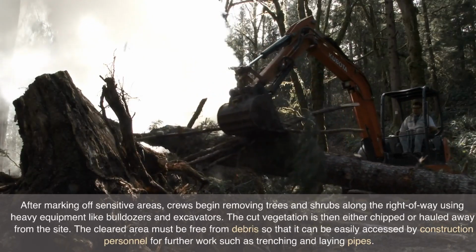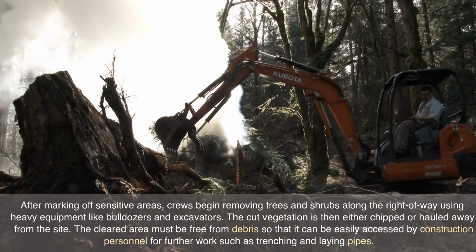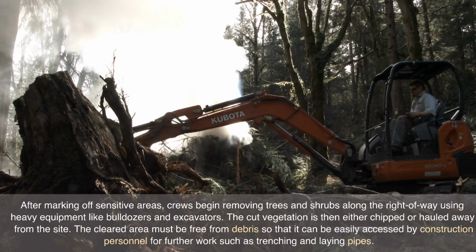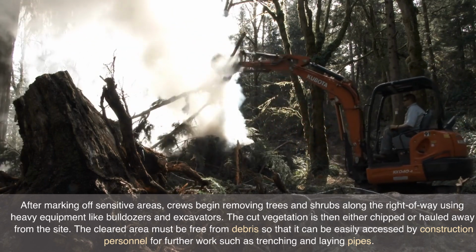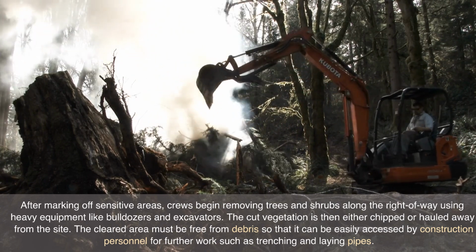After marking off sensitive areas, crews begin removing trees and shrubs along the right-of-way using heavy equipment like bulldozers and excavators. The cut vegetation is then either chipped or hauled away from the site. The cleared area must be free from debris so that it can be easily accessed by construction personnel for further work such as trenching and laying pipes.